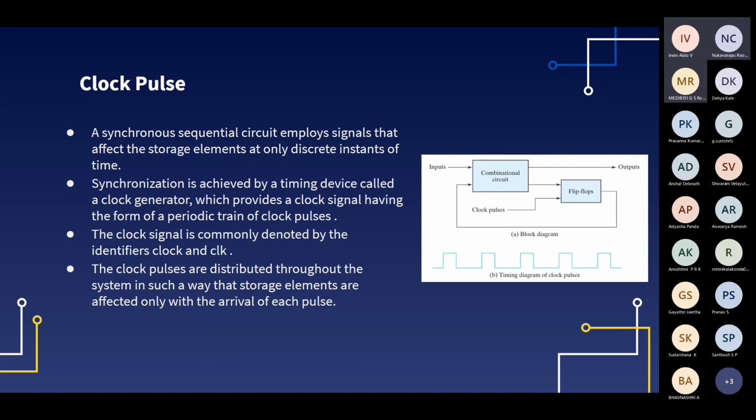So at the instant of 1 nanosecond, only one value of the output will be correct, and the other value will not be correct because it still didn't get the value from the gates. So it's essential to wait till 30 nanoseconds so that we get correct values in both lines. If we read the values beforehand, before the 30 nanoseconds, it will show us an error and cause a major malfunction in our circuit. So it's essential to wait.